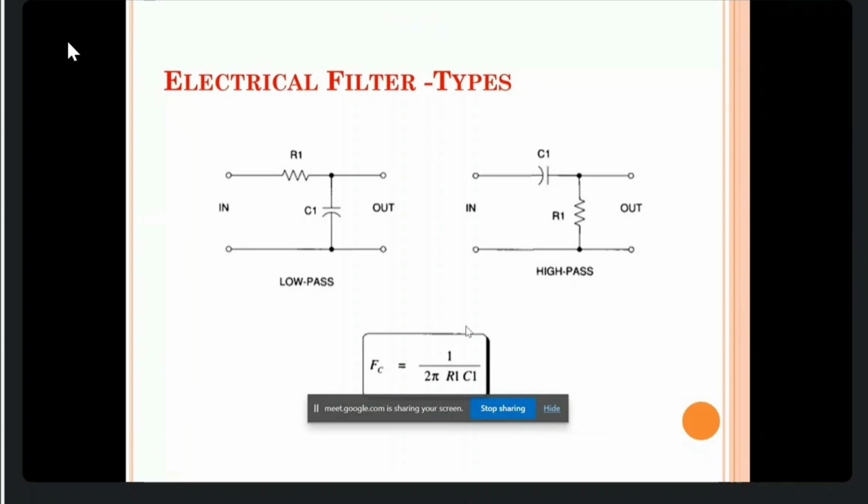The reason is, if the frequency is higher, the component value will become very low. For example, the frequency is in gigahertz. For example, I want to design at 1 gigahertz. So if the frequency is 1 gigahertz, the resistance-capacitance product, or even instead of RC you put LC, this RC or LC product should be 10 power minus 9.